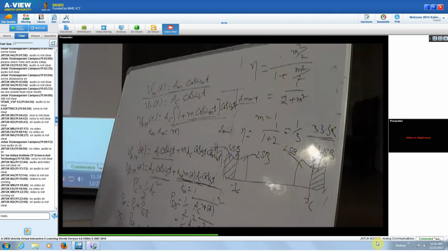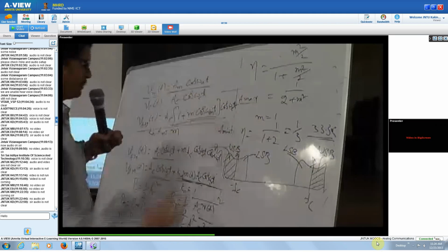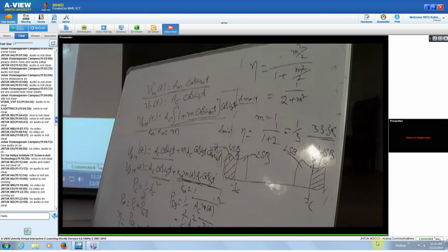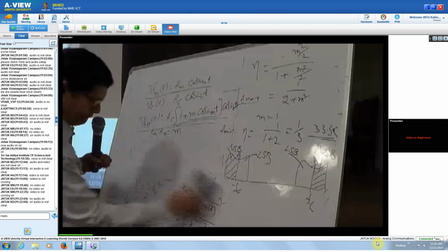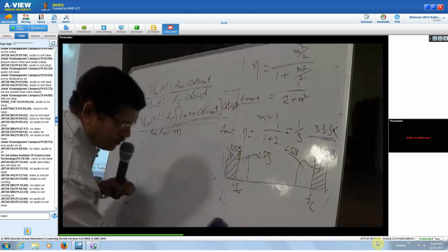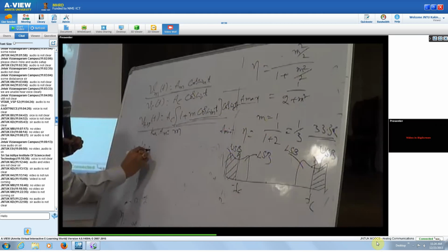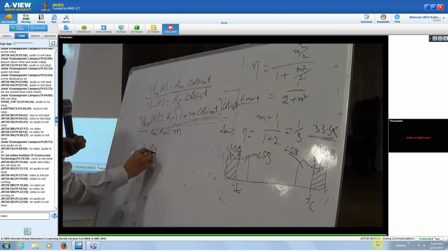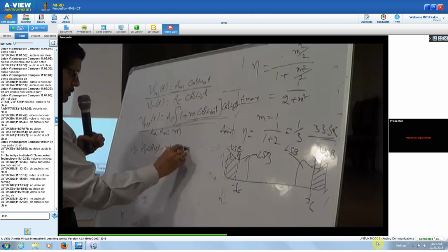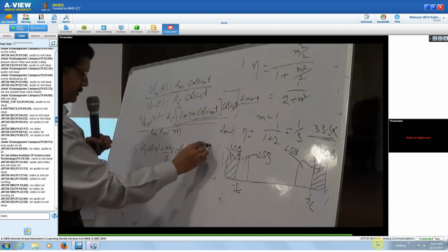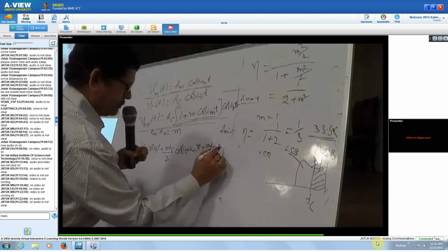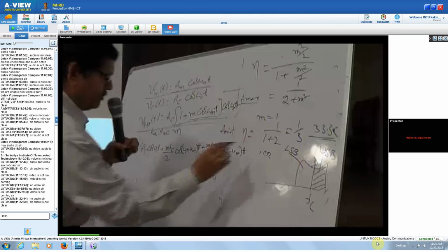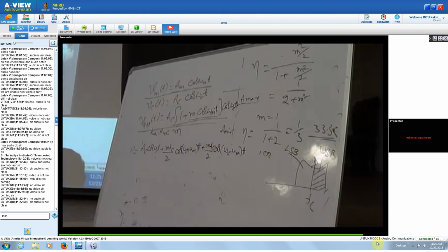So when we say that we have the signal as (1 plus m cos omega m t) into cos omega c t, with a single tone modulation frequency, then we have the signal as Ac cos omega c t plus (m Ac by 2) cos(omega c plus omega m)t plus (m Ac by 2) cos(omega c minus omega m)t. This is the signal content that we have.